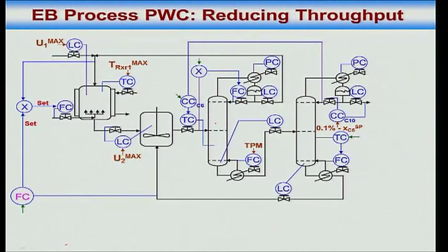Now let us go in reverse. I am at low throughputs, I am increasing the steam here. As I am increasing the steam, all flows are increasing. Flow to this column is also increasing, in ratio reflux is increasing, but then when reflux becomes max, I cannot maintain it in ratio anymore. If I cannot maintain it in ratio anymore, well that's it, then L1 is at L1 max.